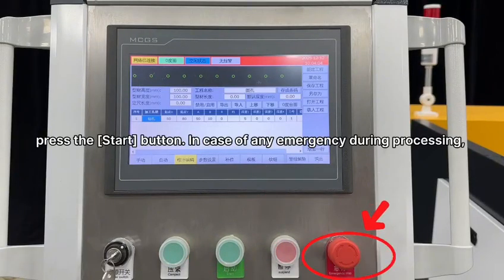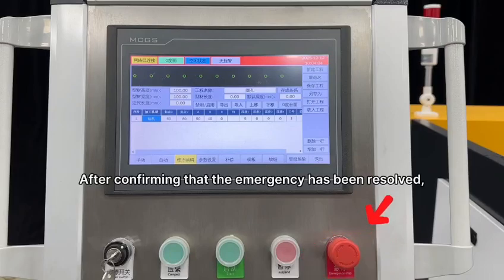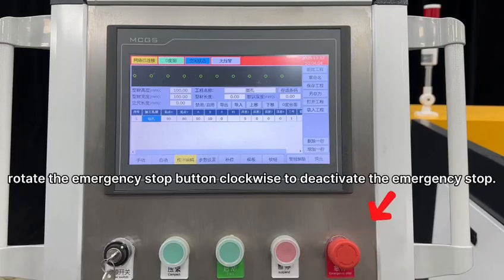In case of any emergency during processing, you must immediately press the prominent Emergency Stop button on the control panel. After confirming that the emergency has been resolved, rotate the Emergency Stop button clockwise to deactivate the emergency stop.